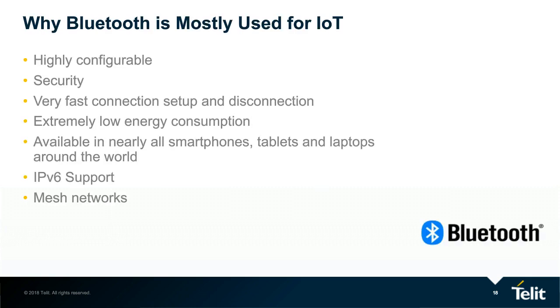So why is it so good? Bluetooth Low Energy in particular is highly configurable. You can set advertising and connection intervals to a few milliseconds or seconds. Either it is very fast or it is very power efficient. Any middle ground can essentially be used, affecting throughput and power consumption. So it can be optimally tuned for your application.